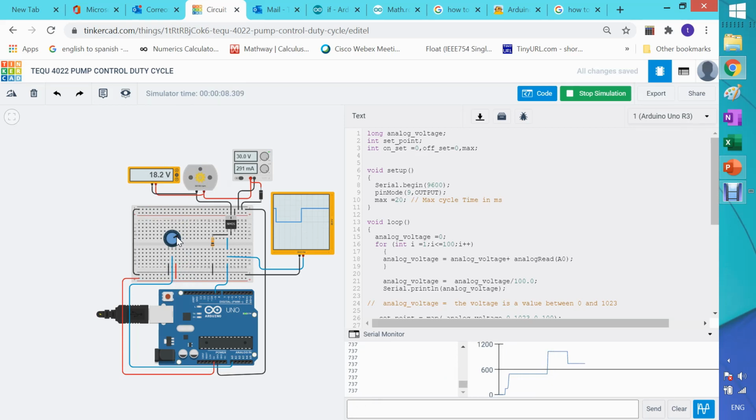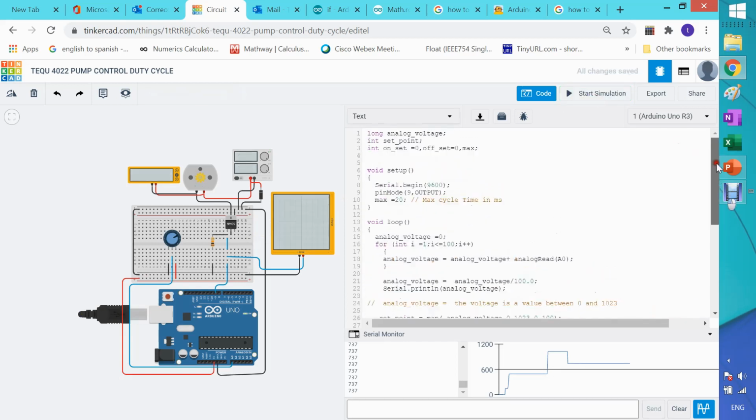And the Arduino can definitely do something else, like for example averaging the analog input, just in case the input from a signal is kind of noisy. You might want to do that. But I can control the duty cycle, or in this case how much of the 20 milliseconds will be on or off, etc., etc. Let's stop here for a second. Let's change a little bit. I can certainly change the duty cycle. Instead of 20, let's put 50, and let's see what happens.